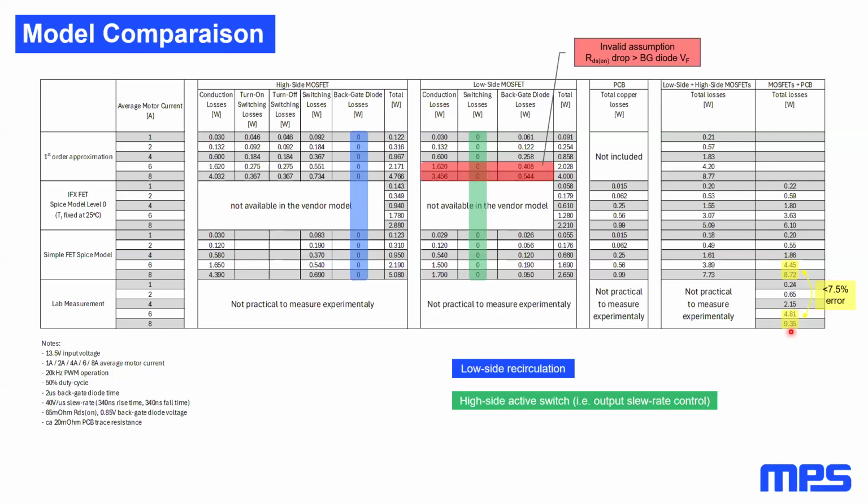The first-order approximation is surprisingly not far from the simple MOSFET test bench results. In our case, we have also included in the RDS(on) its increase with higher currents based on an educated guess and approximation of the junction temperature at the different current levels.